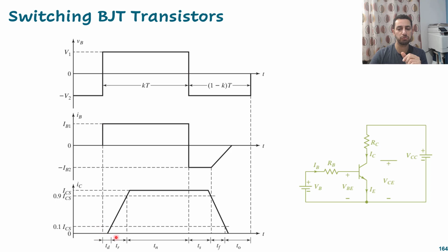We have mentioned that before. I think you know what the delay time and rise time are. After that, it goes to the conduction period, the on period. To keep it in the on period, you have to keep supplying current to the base. When you decide to turn off that transistor, you have to supply maybe 0 volts, and better, you have to supply negative volts.